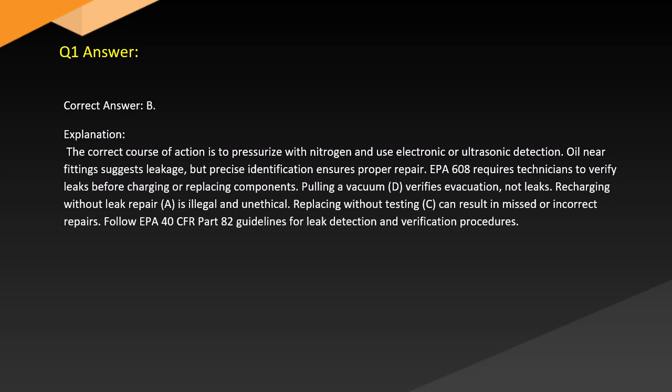Pulling a vacuum (D) verifies evacuation, not leaks. Recharging without leak repair is illegal and unethical. Replacing without testing (C) can result in missed or incorrect repairs. Follow EPA 40 CFR Part 82 guidelines for leak detection and verification procedures.